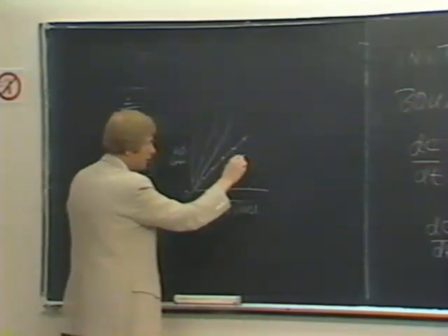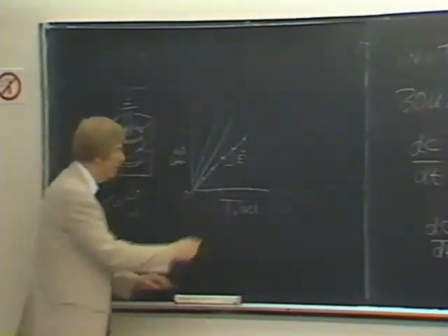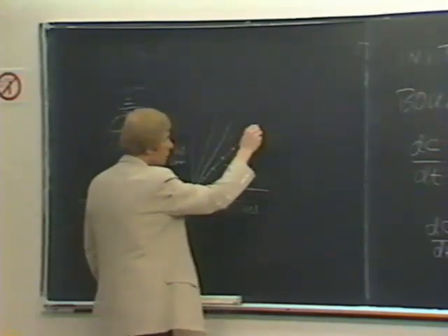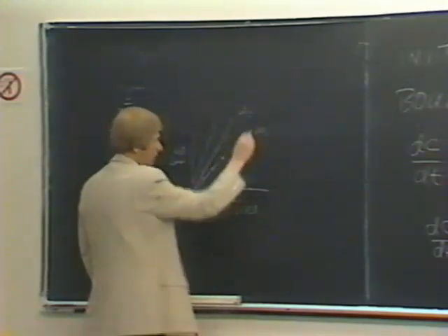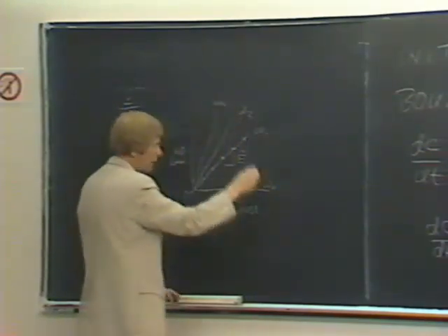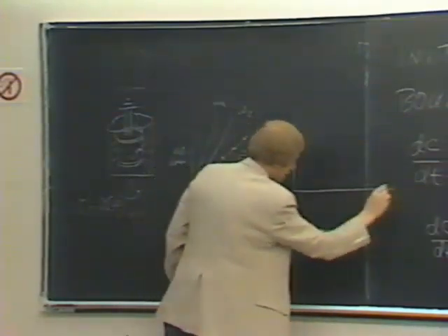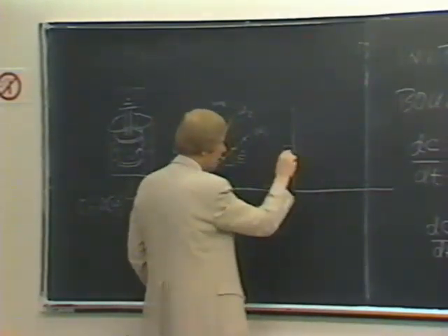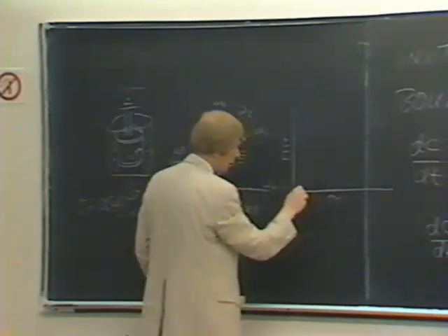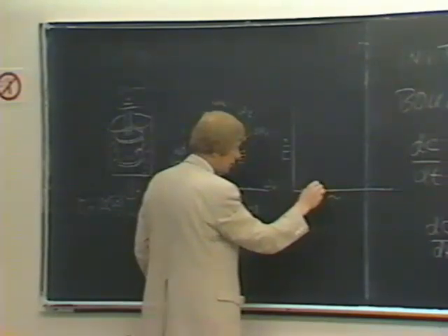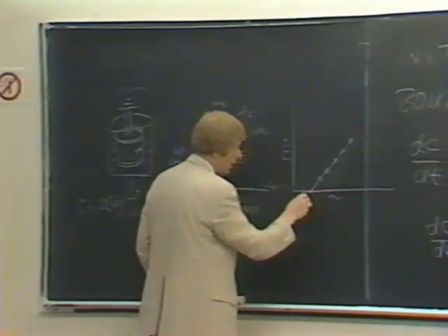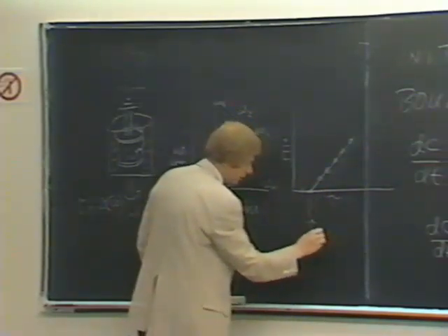Then we can plot the erosion rate against omega 0, omega 1, omega 2, and so on. And for each omega, we have a shear stress. And if we plot erosion rate, the slope of this, against the shear stress, then we find that we have low values, and then we get a value like this. And this is tau critical for erosion, and the slope of this is your M.